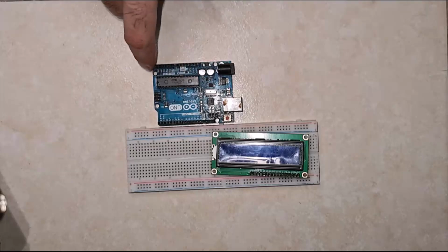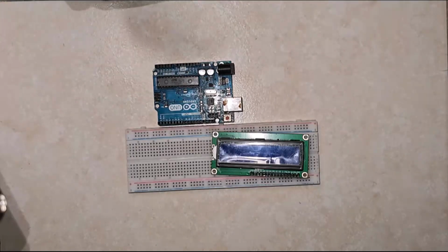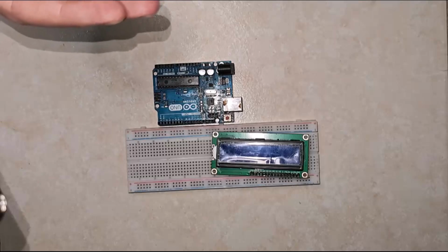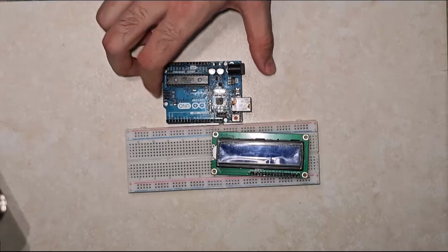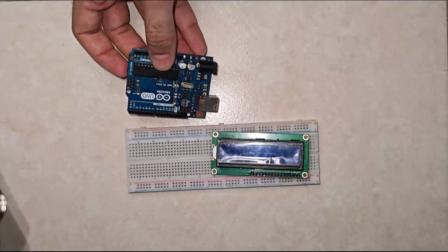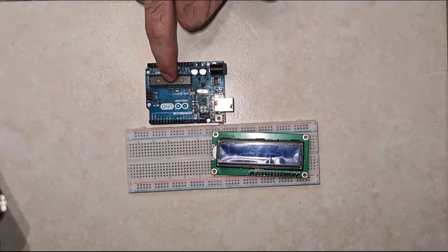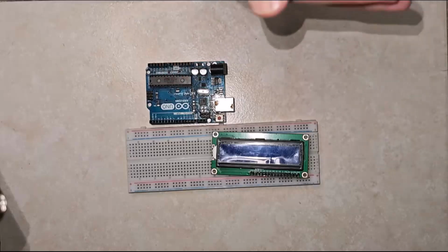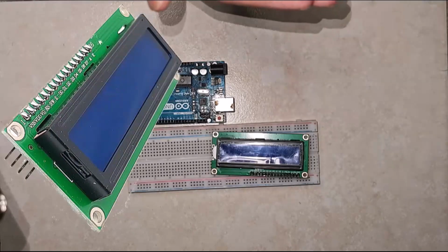These pins, I mean pins A4 and A5, are not just analog inputs. They have a dedicated hardware module inside the microcontroller. See, this is our microcontroller. They have a dedicated hardware module inside of this microcontroller that handles all the precise timing, start-stop conditions, and data shifting that is required by the I2C protocol.